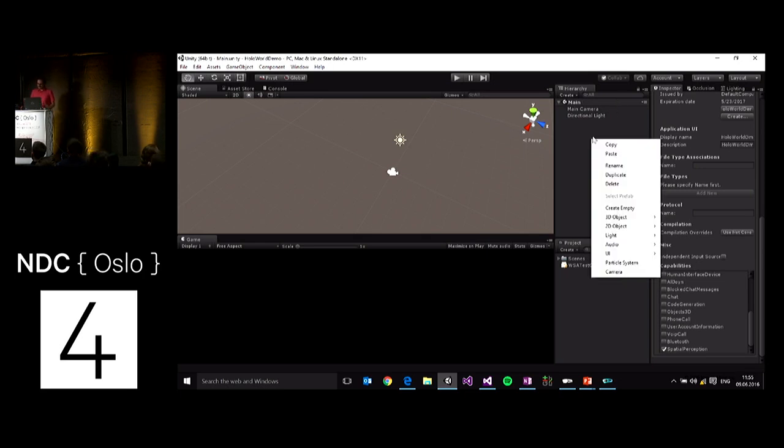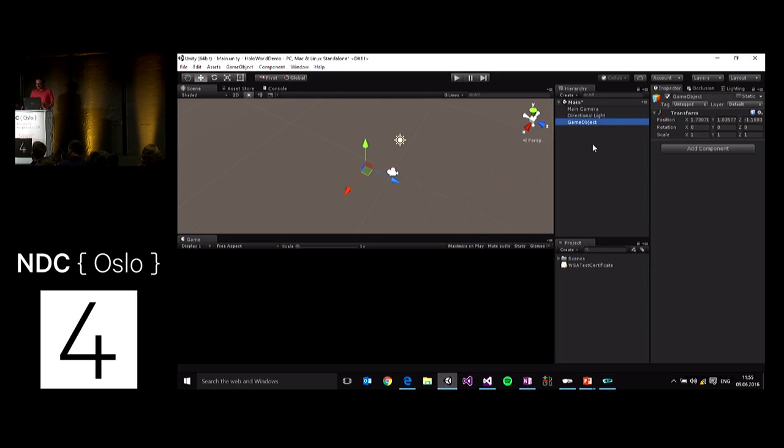Let's actually add some objects. What I usually do is create an empty game object as a container where I can place objects that belong in the same physical location together and group them. I will tell you at the end why I do this and why it makes sense. So reset the position and set it a bit further away from the camera. We set it like 50 centimeters lower and 2 meters in front of the camera, which is usually a nice way, when you start an application, for the holograms to start about 2 meters in front of the user's view.